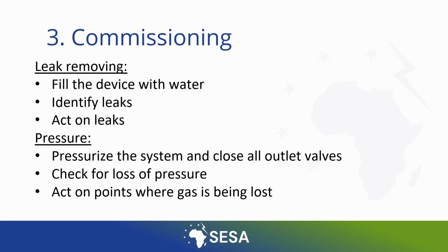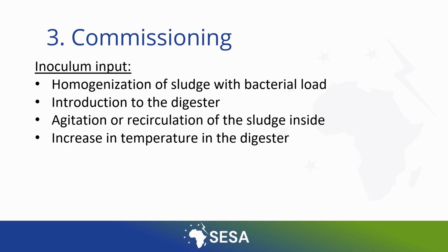Once it has been verified that the plant has no liquid or gas leaks, it must be emptied of water in order to incorporate the acclimatized inoculum. Organic waste contains a very small amount of anaerobic bacteria. This makes it very difficult to start the biological reaction with this byproduct.